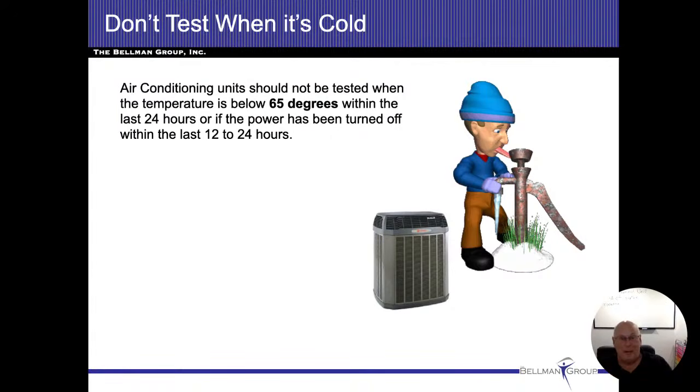So you might go to a house, you're inspecting the home, and then you look at the air conditioner, and it might be just fine. But you turn that air conditioner on and the refrigerant inside that compressor or around that compressor is a liquid. Now you're going to be pushing that liquid through the compressor, and that's just going to damage the scroll coils and everything else. So we don't want to take that chance. We don't want to damage the compressor whatsoever.